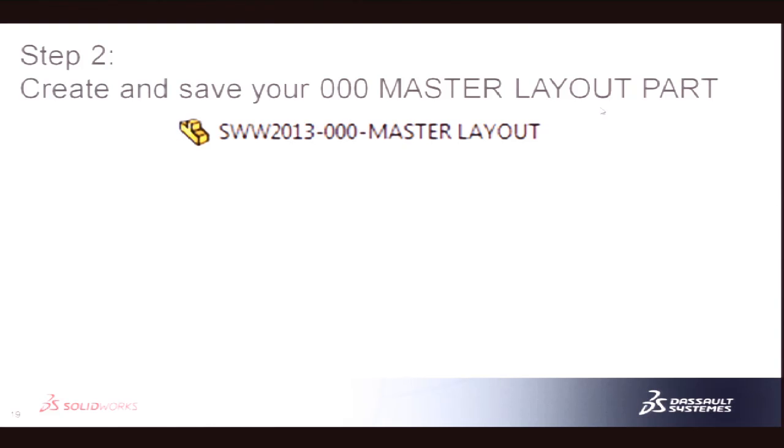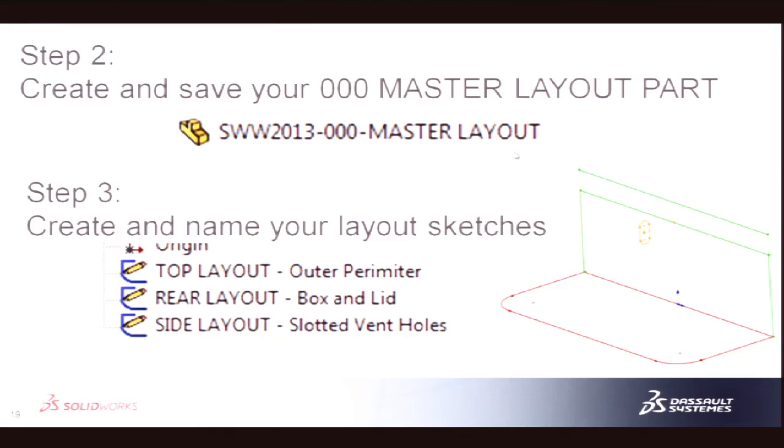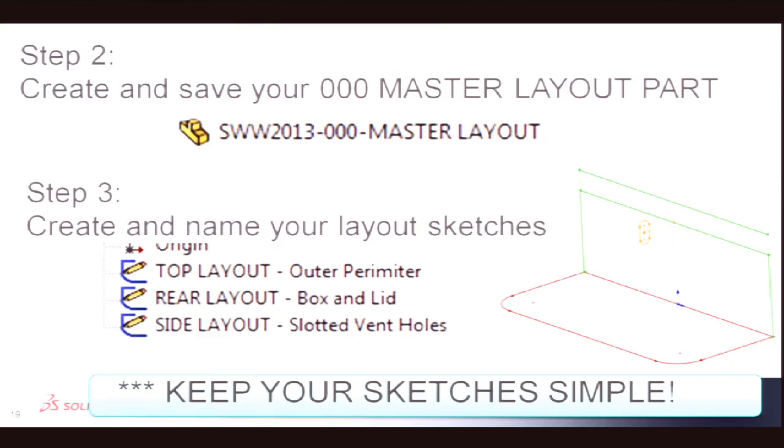So you create and save your first master layout part, and after you create and save that first master layout part, you're going to create and name your layout sketches. So you create your layout sketches, you give those sketches a name so they're easy to find in the tree. Oh, more cyan. Nice. All right, keep your sketches simple.